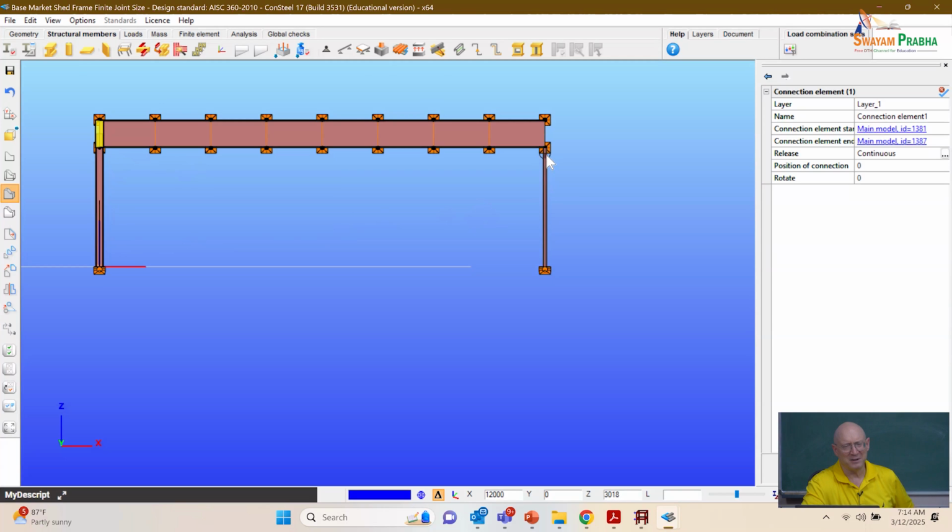I noticed in the Indian IS 800 code, I think it basically said, no, you should always design the member as center line to center line. But here, this would be an argument that in some contexts, no, it would be more appropriate to consider that member goes from the base plate to the bottom of the roof girder. And then same thing for the HSS section over here. It's a little bit shorter.